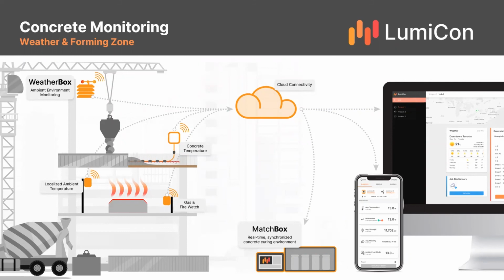So monitoring above the concrete and also underneath the concrete is important, specifically for high-rise projects when we are in the forming zones and we are using heaters. Monitoring the temperature under the forming zone and making sure that the heater is doing the job is important. And again, there are other byproducts when we are using the heaters, for safe operation at the job site, like hazardous gases like CO and H2S that come out of this.